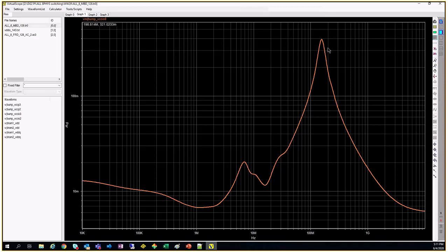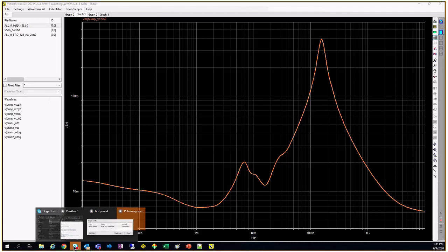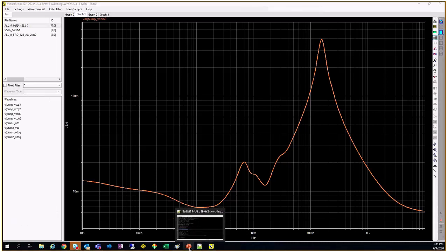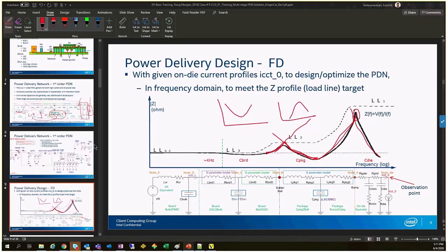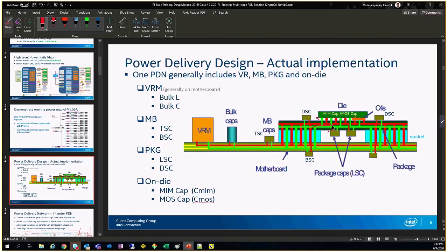So if you improve your package routing, how you go from, I explained, you want to go as vertical as possible. You are the PA engineer, your aim is always to go as vertical as possible. You want to go from here to here directly. You want to reduce this path like this. You don't want to go like this. You want to go directly like this. This is your preferred way. You don't want to go like this, then come left, then come up, then come right, then come up, like that. So as much as possible, you go straight up.